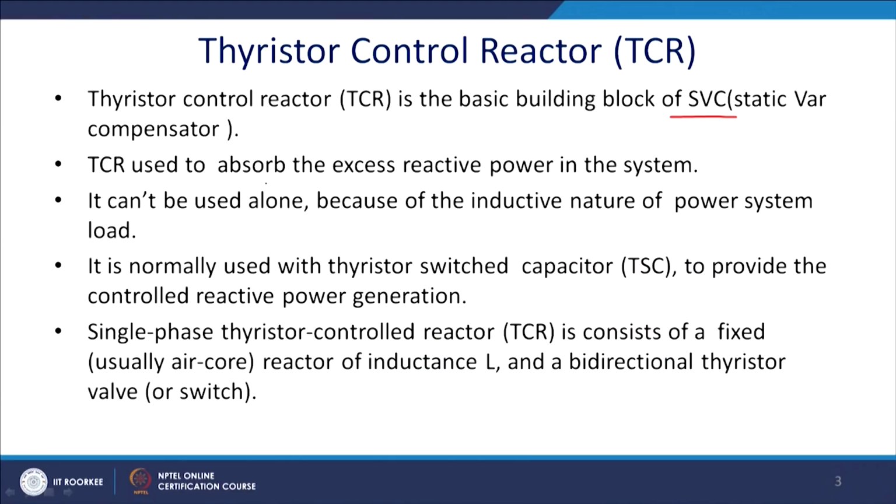The TCR is used mainly to absorb excess reactive power in the system. We will see the switching and how it absorbs the extra reactive power, and thus improves the power factor and other related power quality issues.